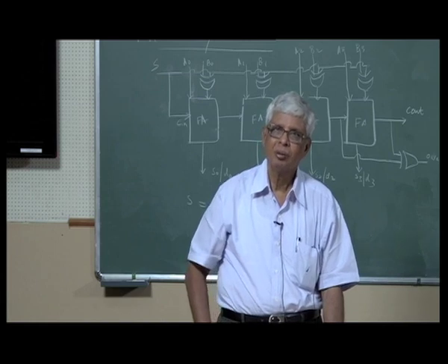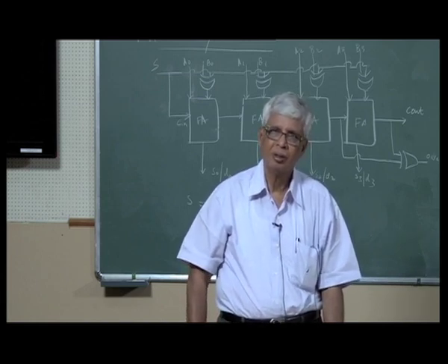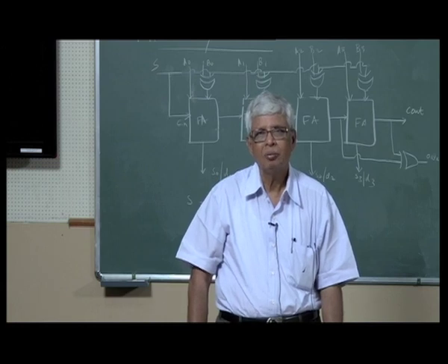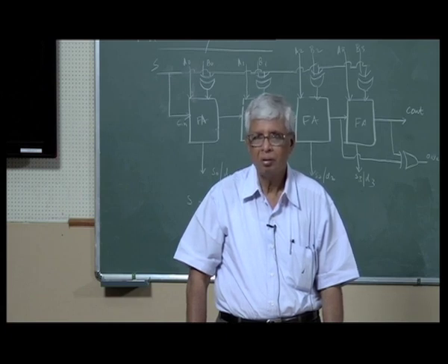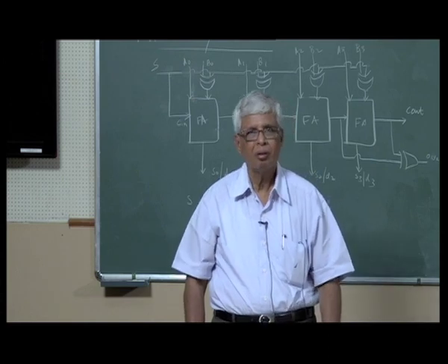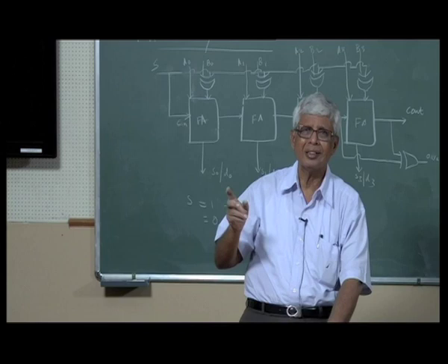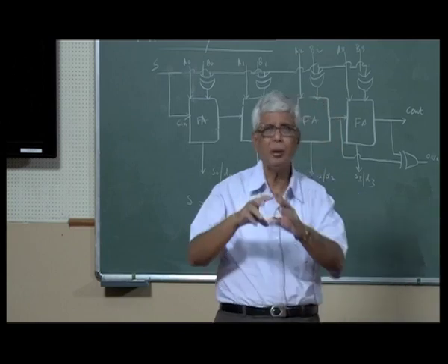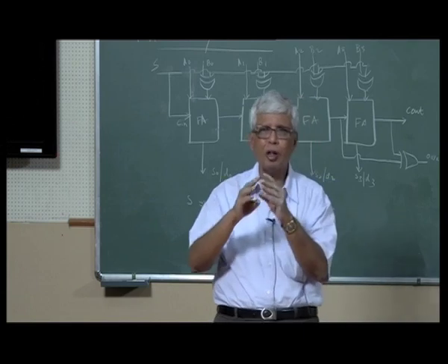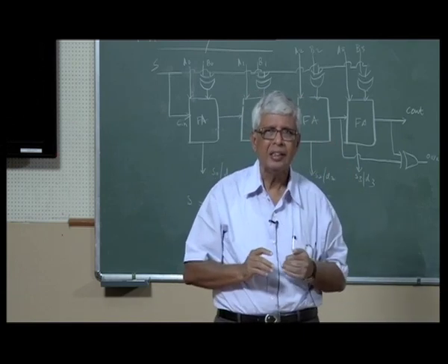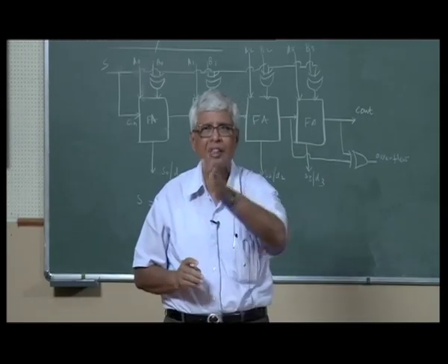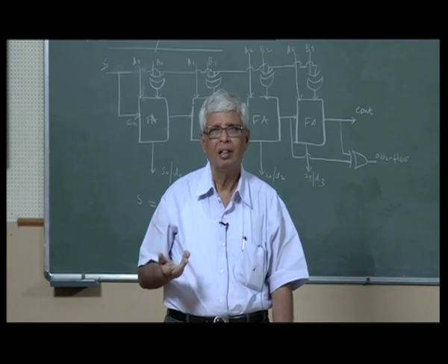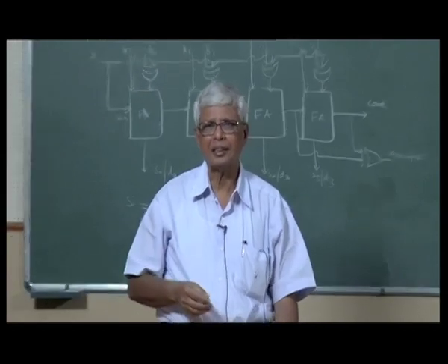Sir, as you said, we can have 17 bits. For that, we have to add one separate adder. So when we will be supplying signals to that 17-bit adder, the codes which we will be forming from 0 and 1, sir, how the 17th code will come out? The 17th bit also you have 0 and 1. Everything is only 0 and 1. See, 16 bits, how are you going to feed the inputs? 16 A's and 16 B's. Now you have a 17th A and 17th B which you feed to the 17th full adder. I don't think there is any complication there.